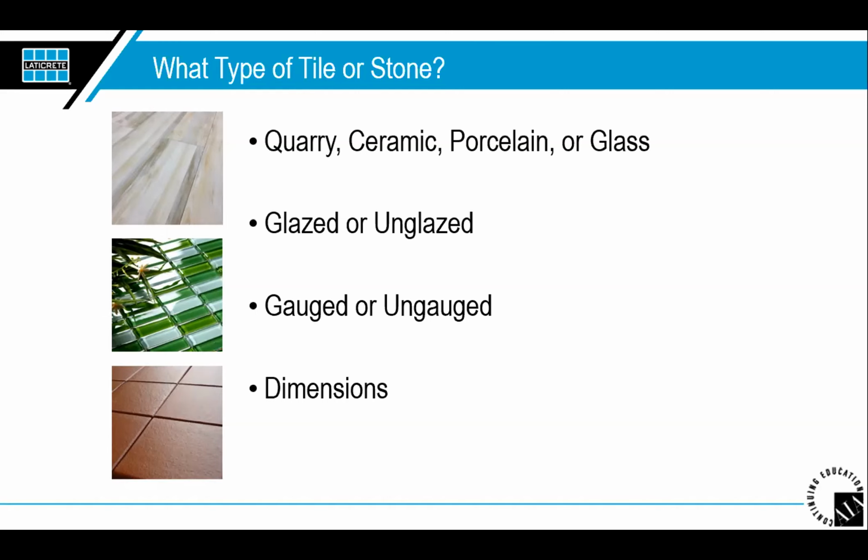So depending on the stone that you pick, we may need to consider that during the specification process. And that's going to come down to knowing the product itself and talking with the manufacturer again about what they want, how they want that installed. In most of the porcelain ceramic facilities, they're going to be open to have that conversation with you if you call, if the instructions are not already on the box.